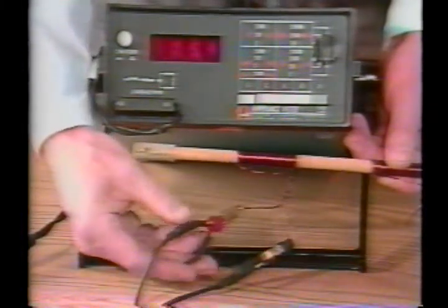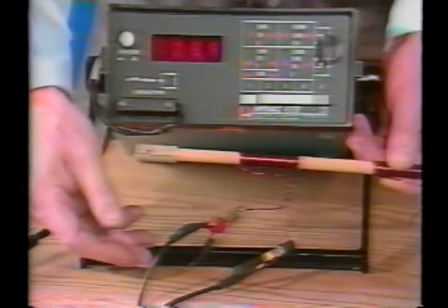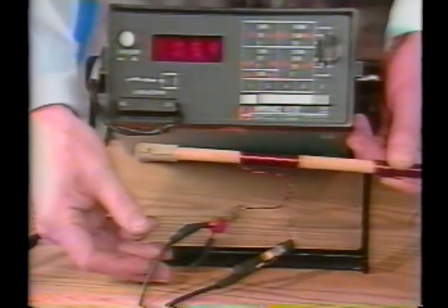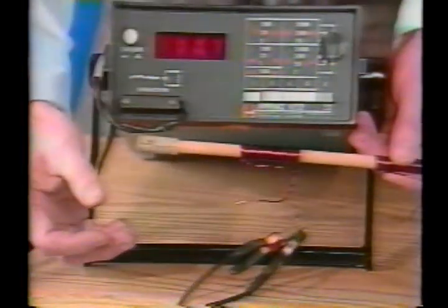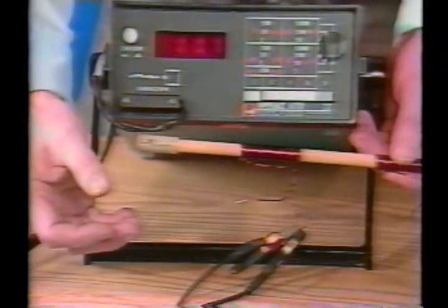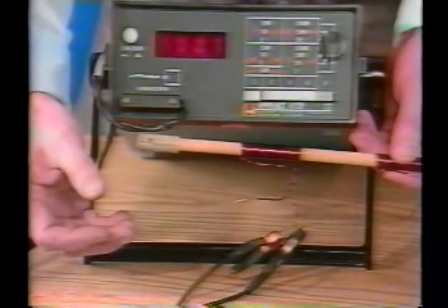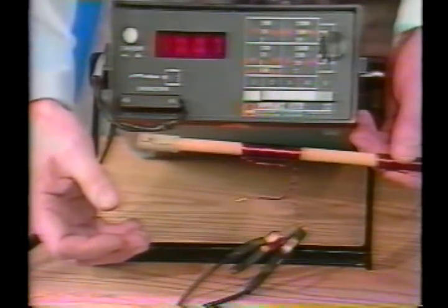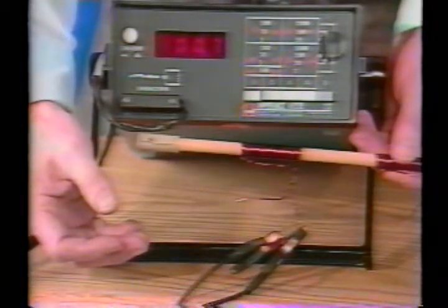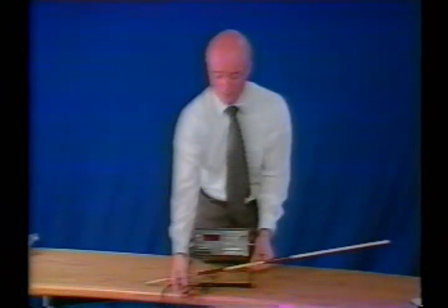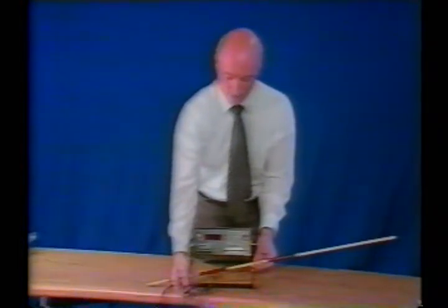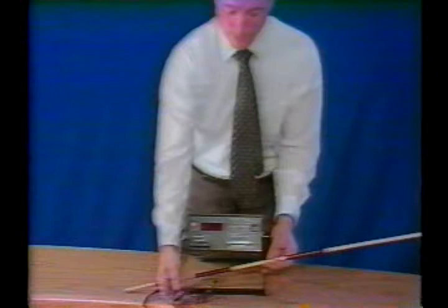We now measure the inductance of the coil with double the number of turns, but also double the length. Doubling the number of turns n, but also doubling the coil length d, should result in double the inductance. The inductance meter now reads 11.2 microhenries. Subtracting the 0.7 microhenry lead inductance gives a corrected coil inductance of 10.5 microhenries, about double the inductance of the first coil of 5.2 microhenries, as it should be.